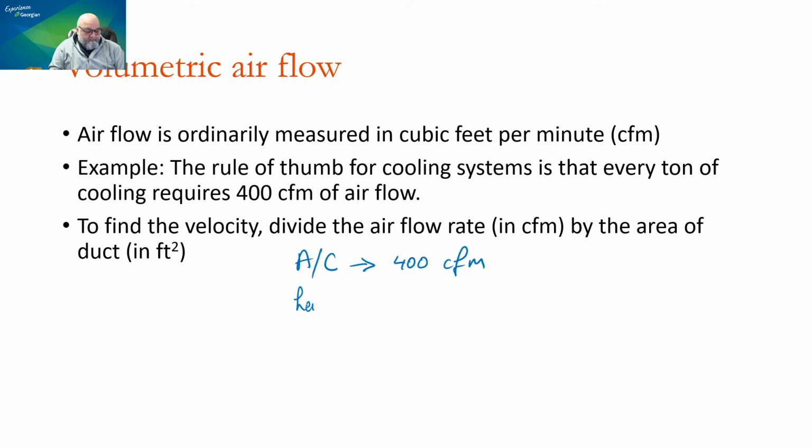For heat pump, you need 450 CFM. Obviously, this is not engineering. This is a rule of thumb, but you're going to be asked on the G2 exam, and well, guess what? 3 marks.